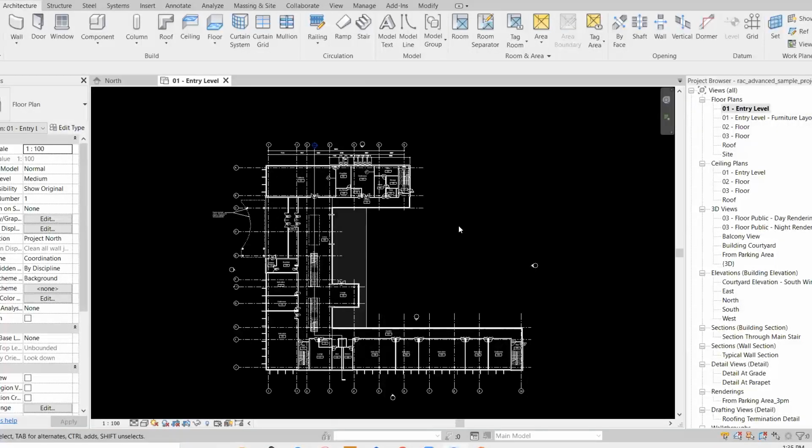Once we prepare that, here in Revit we have one more option. As I mentioned previously, we always depend upon architecture. So the architecture team can prepare the levels and grids, project base point, site base point, and those kinds of basic settings and coordinates. They get the basic settings done and ready, and then they prepare the levels and grids in the architecture model. So what we need to do is link the Archi model in our MEP template or MEP project, both the same. If we link that, with the help of the copy monitor option, we can take the levels and grids from